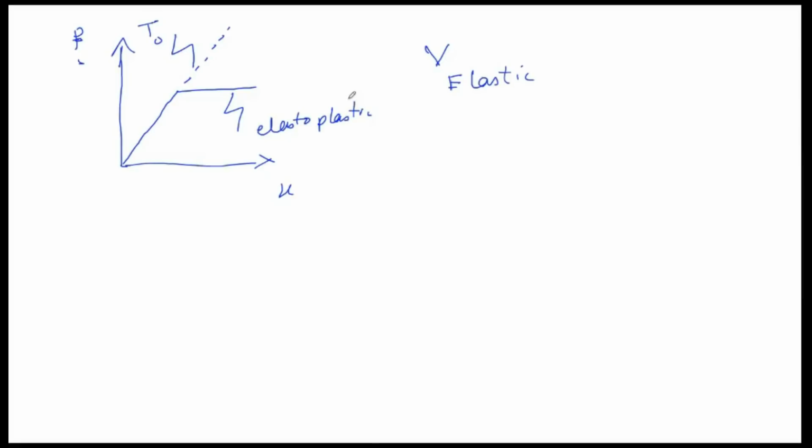And it is known from many past experimental works that the actual force deformation behavior of the structure is not linear, but rather has an inelastic or non-linear behavior, which can be idealized as elastoplastic. This is the corresponding linear elastic system.